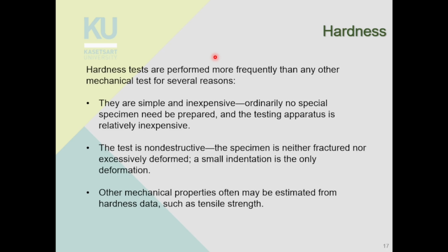So when you buy a new phone, what is the first thing that you normally do? You would put on a protective film, a screen protector, right? But why? You might think that you don't want to break the screen, and you would choose a screen protector that is really hard, with really high hardness. But actually, high hardness doesn't help if you drop your phone. If you drop your phone, the screen protector with high hardness doesn't help you at all.